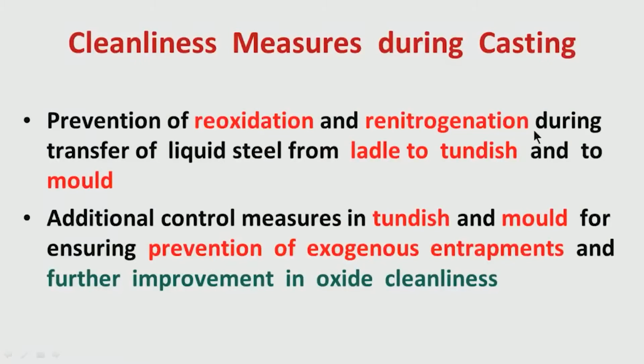So, all the steps which you have taken for secondary refining, for cleaning, should not go to waste. How do you do that? Because in casting, what you have to do is prevent reoxidation and renitrogenation during transfer of liquid steel from ladle to tundish and to mold.